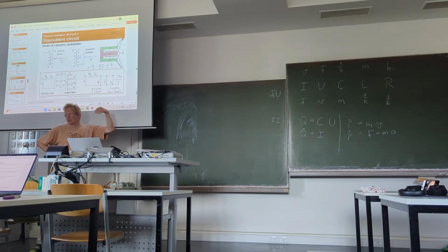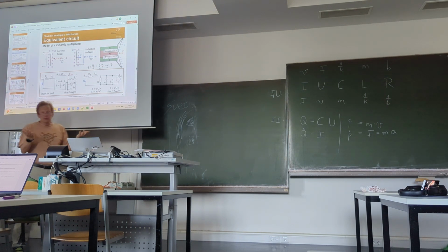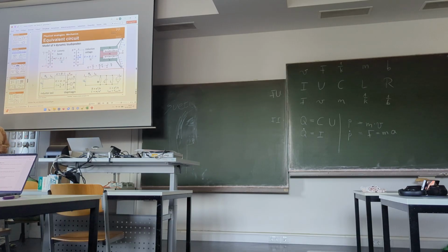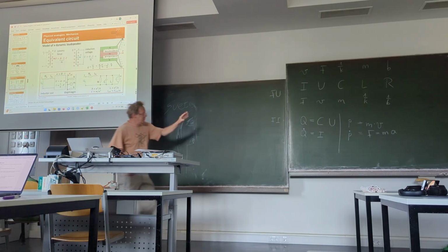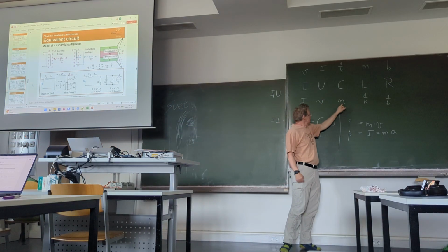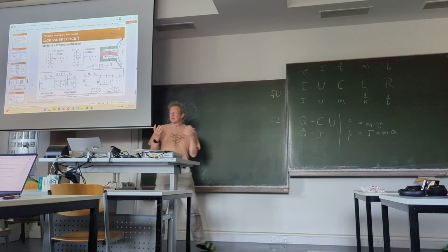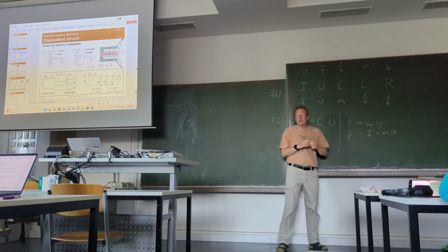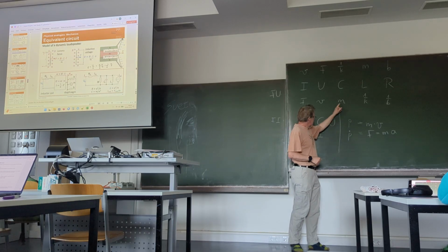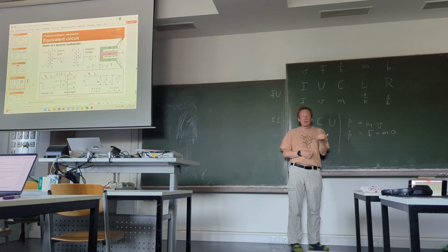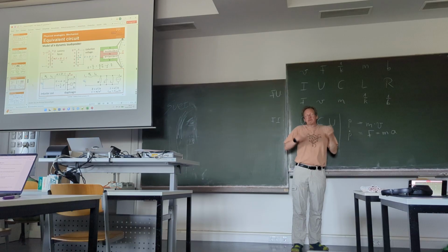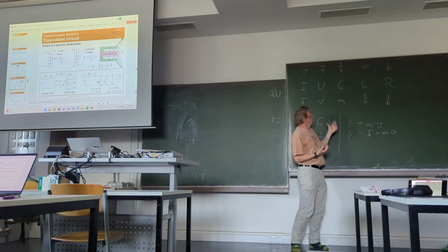And if we have an external force, then this looks like a source, not a current source. We have then here formulas, and it's not just an analogy. So here we just said capacity corresponds to a mass. In the simulation, you could just use the same numbers if you're working in SI units. So for example, a mass of 2 kilograms becomes a capacitor of 2 farads.